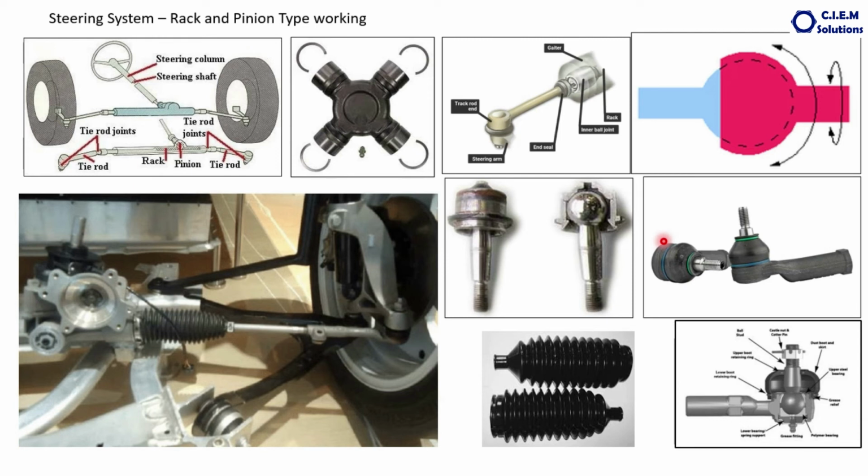whenever we need turning, we turn the steering wheel, and through that these tires are moved through this linkage, through this rack and pinion. But as long as the turning is over and the road becomes straight, when you release the effort on the steering wheel, it automatically returns to the center. Means the tires automatically return to the straight line position. How does it happen? How do they automatically come to the center line? That happens mainly because of the steering geometry. There is an arrangement called the caster angle, which we'll talk about exclusively in the steering geometry video. Because of the caster angle, the tires become straight automatically as soon as the effort is released on the steering wheel.